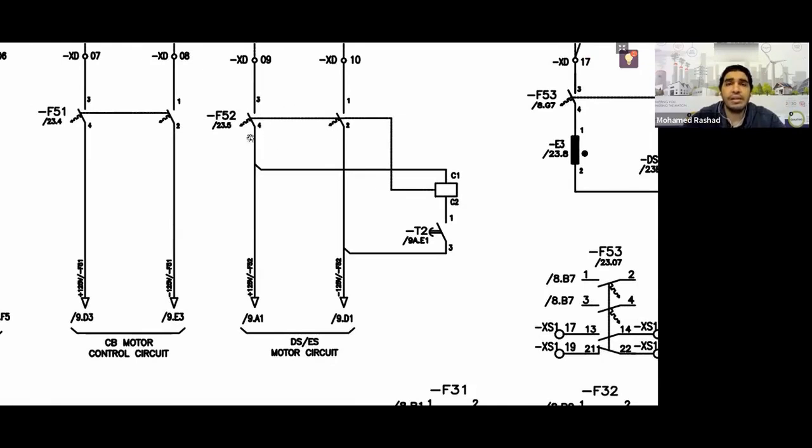What will I do? It comes here to this MCB, guys, which is the miniature circuit breaker. It is installed next to it mechanically, meaning that the miniature circuit breaker has an opening on its side. A small device is installed with this opening and connected to it through this hole. The part inside is like what we saw in the switch: a coil with an arm. As soon as you apply voltage to this coil, it pulls the arm, causing it to trip or disconnect.